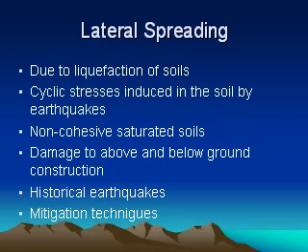So today, in our discussion of lateral spreading, we discovered that lateral spreading is due to the liquefaction of soils. We found out that cyclic stresses induced in the soil are caused by earthquakes, which in turn lead to lateral spreading. We know that lateral spreading from liquefaction is possible only due to the liquefaction of non-cohesive saturated soils. There are also other parameters that can eventually lead to liquefaction, but basically non-cohesive saturated soils are what liquefies.